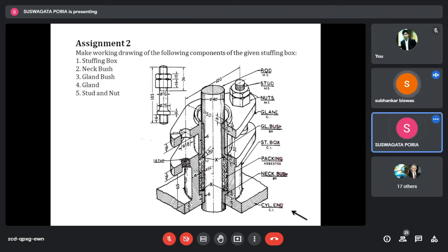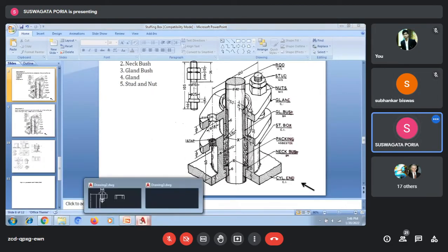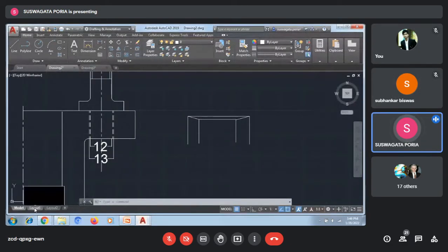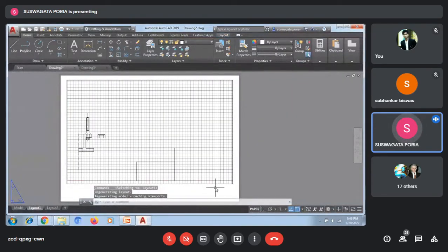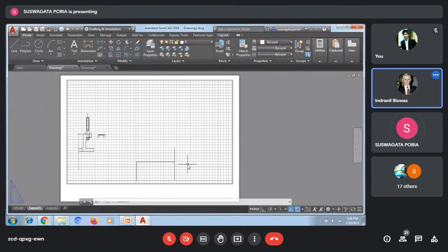You have to convert it into PDF, A3 template PDF with title block. My suggestion is that at first what you will do in AutoCAD, okay, I'm showing you. You will make a layout with A3 template and the title block will be there. You know how to do it. You told me yes, sir. Okay. So you will make that A3 template with a title block. Already you will keep it on your desktop. Okay. A blank template with title block where all the information is written.